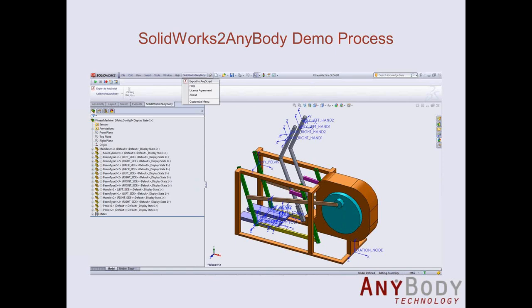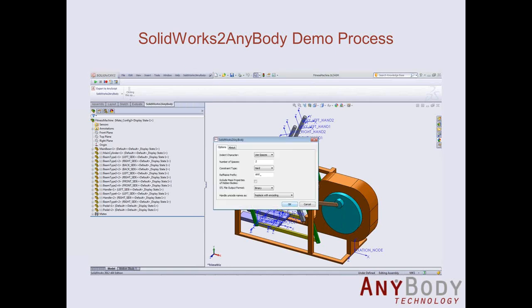From this page, I will demonstrate how we can use the SolidWorks2AnyBody add-in application step by step. So first, if you click the menu SolidWorks2AnyBody, then you can see a pull-down menu. Among them, you can click the Export to AnyScript menu. After that, you can see a dialog which contains several options for the translation result.